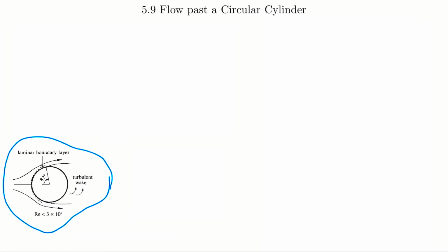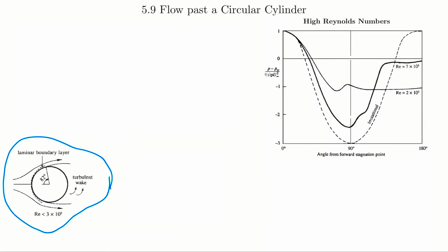The pressure in the wake downstream of this separation point stays nearly the same, and it's lower than the upstream pressure, okay? So I'll show that here. The point of stagnation would be right here. That's our non-dimensional pressure, so P minus P infinity, divided by half rho U infinity squared. And then we've got the degrees, they increase from 0 degrees. Our pressure here is decreasing, so that's a favorable pressure gradient, less than 0. Then the moment right here where it starts to increase, we end up with separation. So we said right at about 82 degrees, somewhere in this region right here, we get separation.